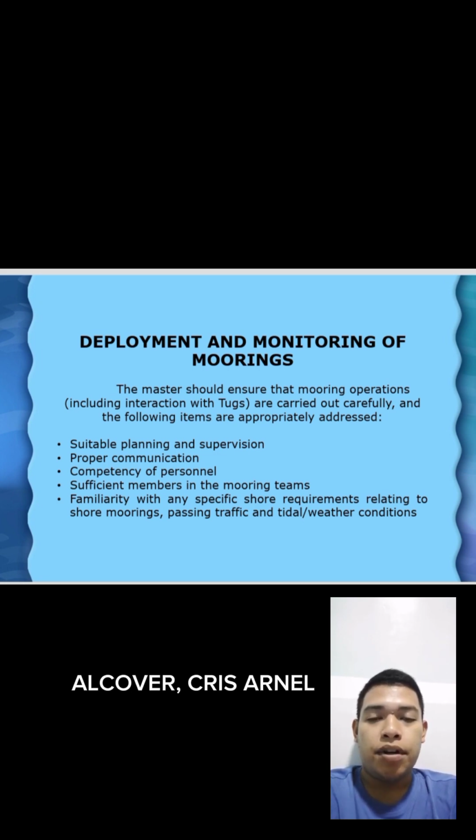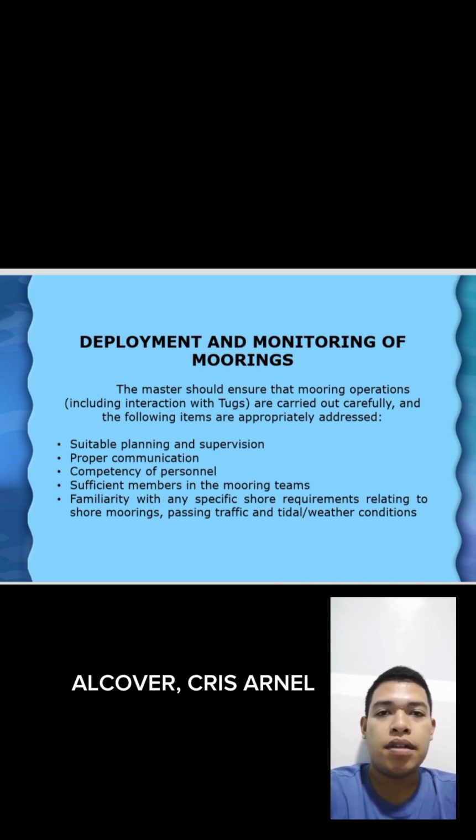Second, proper communication. Third, competency of personnel. The fourth one is sufficient members in the mooring teams. And the last one is familiarity with any specific shore requirements relating to shore moorings, passing traffic, and tidal or weather conditions.